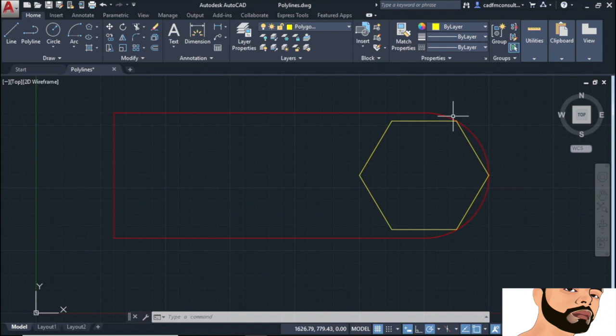Okay, last but not least, we're going to go to the Layers panel again and click on the drop down and select Splines. Now, splines are basically irregular curves following a group of given points, and they use a thing called NURBS technology, N-U-R-B-S. So whenever you're working with somebody with AutoCAD and they mention NURBS, it's a non-uniform rational B-spline.